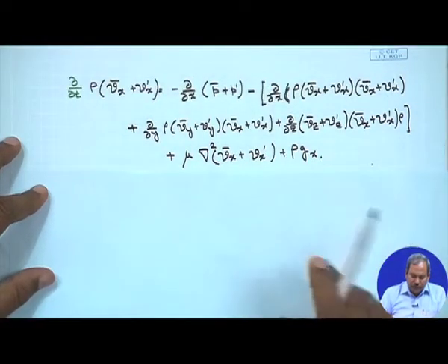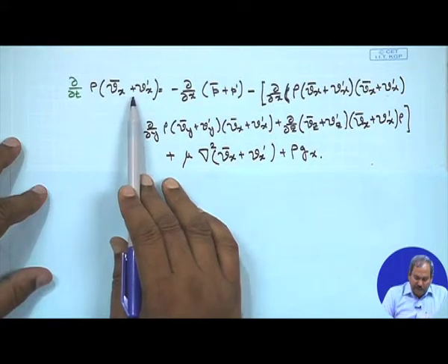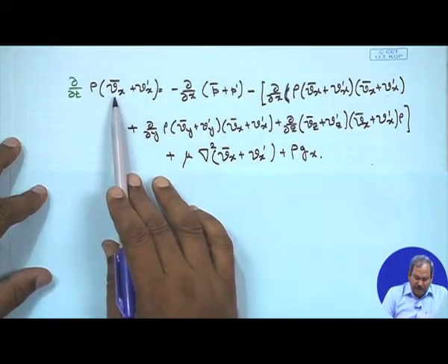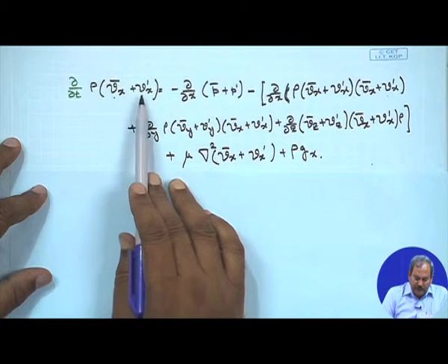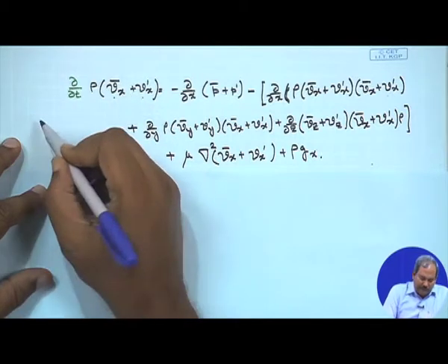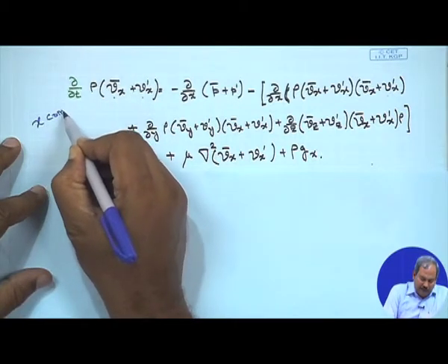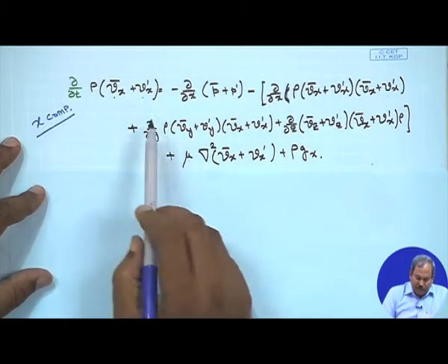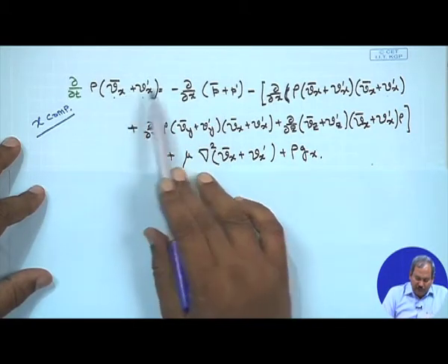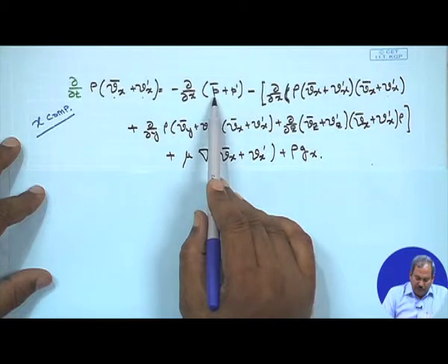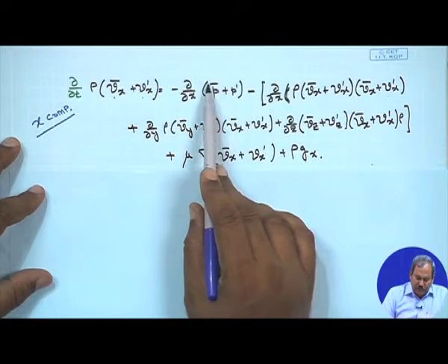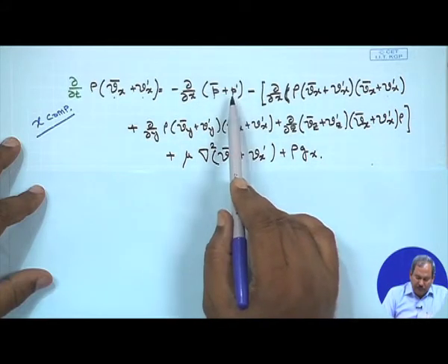So, now we move on to the Navier-Stokes equation, the equation of motion, where all velocities are expressed in terms of a time smooth velocity and a fluctuating velocity. This is written for the x component of the Navier-Stokes equation. Similar to velocity, when we come to the pressure term, the pressure will also, in turbulent flow, have a time smooth component and a fluctuating component.